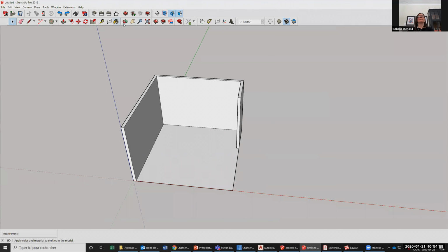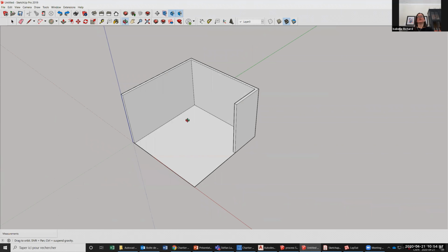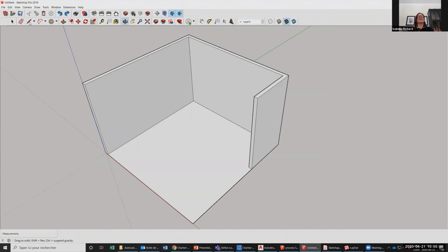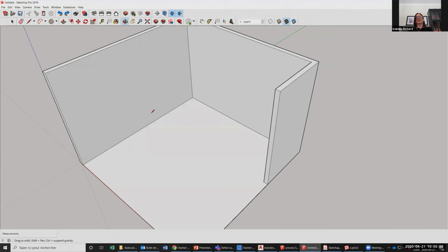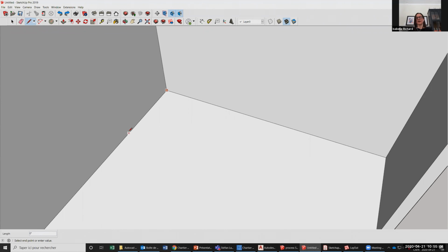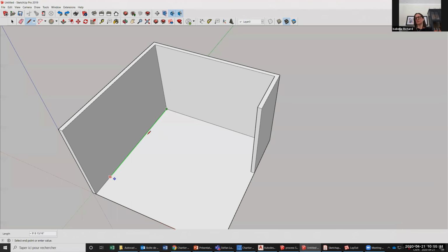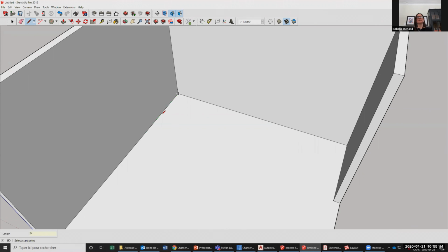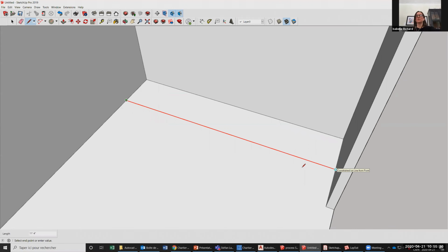So now, once you draw over a face, already done face, let's say, for example, I start from an endpoint and then force direction towards the front of my room here. I go 24 inches. And then it creates a new segment that you don't see, but it creates also another endpoint. Endpoint that is a guideline for you to start a line that you want to do all across from 24 inches from the back. You want to make another line, so that's how you do that.